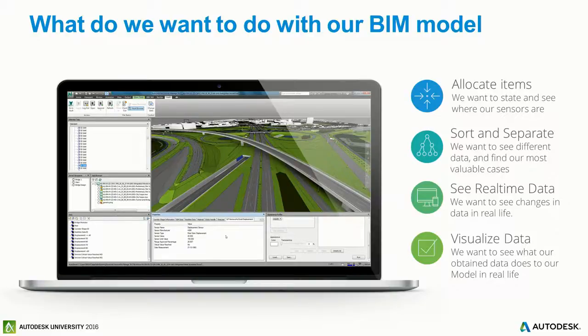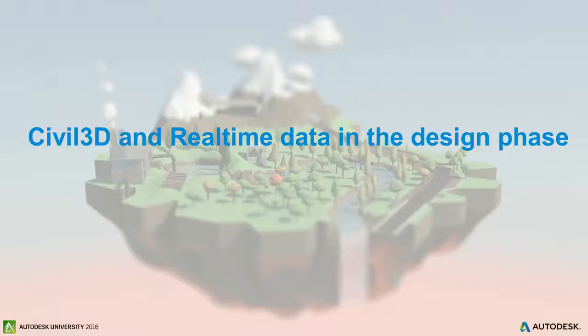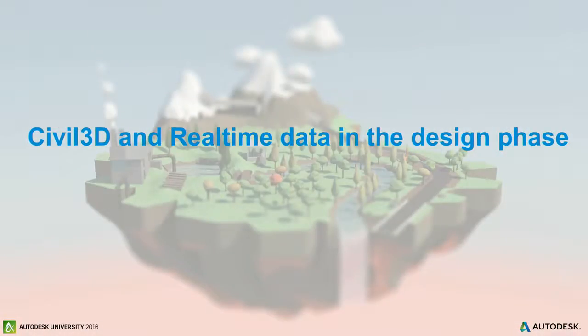And the last part is I want to visualize my data. So I want to have easy tools. So I push a button and I see, oh, right, here it's not going as was planned, or here it's not anymore to the requirements we wanted to have. So that's the visual side of our BIM model. So now we know what we want to do in our BIM model. So now we are going to look at the steps, how to get there. And I myself use a lot of Civil3D, so I thought, oh, I'm going to do it in Civil3D. And then in Navisworks, and we're going to see what happens.